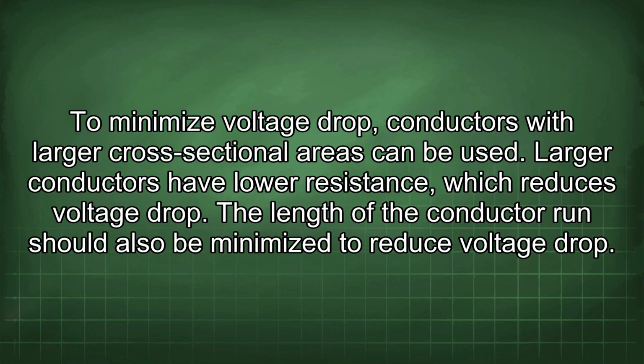To minimize voltage drop, conductors with larger cross-sectional areas can be used. Larger conductors have lower resistance, which reduces voltage drop. The length of the conductor run should also be minimized to reduce voltage drop.